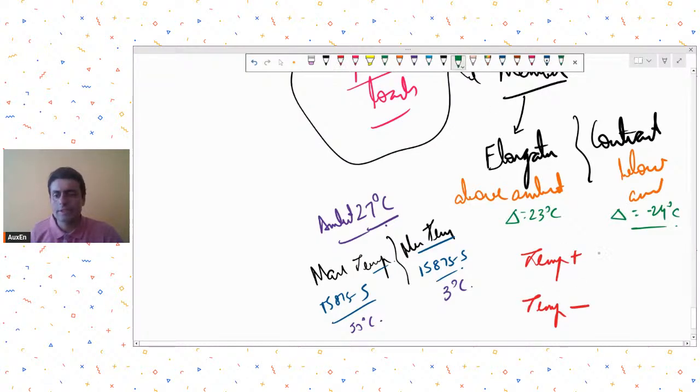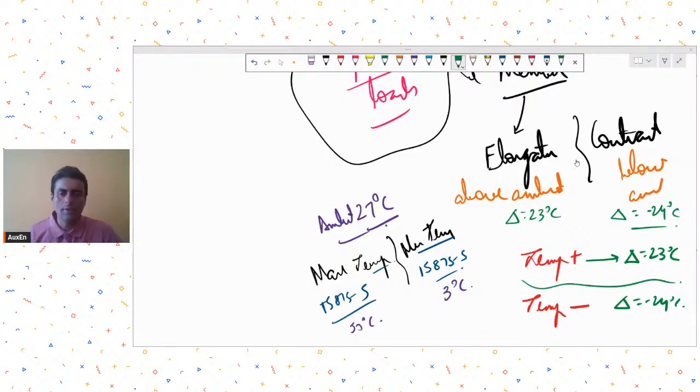In these load cases, put these values and apply them to your members. The software will automatically calculate the elongation and contraction, and based on that it will calculate the restraining moment, shears, axial forces, etc. This is the normal way given in IS 875 part 5.